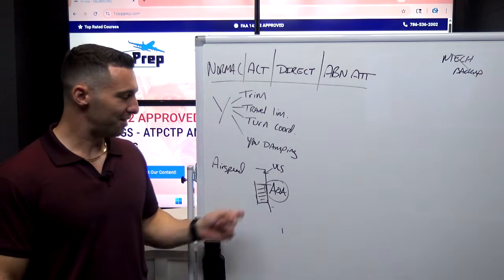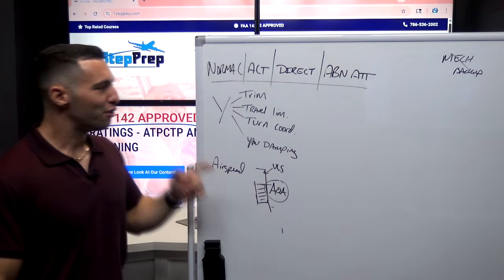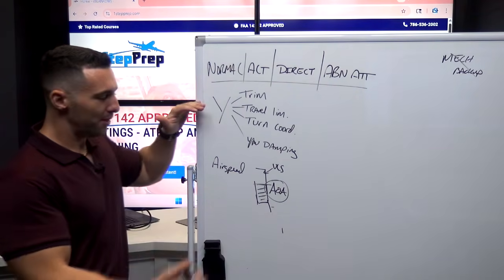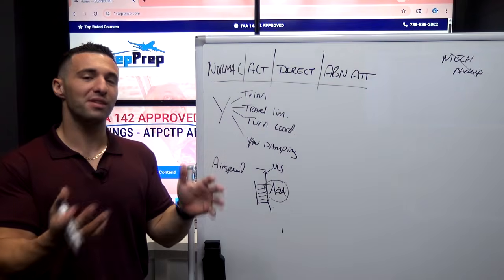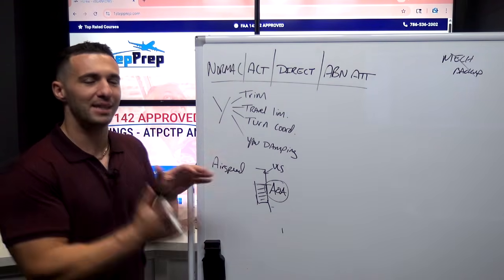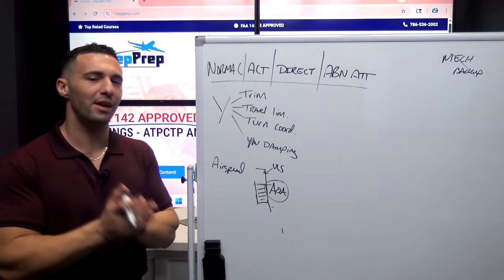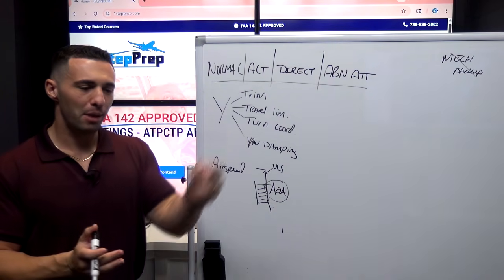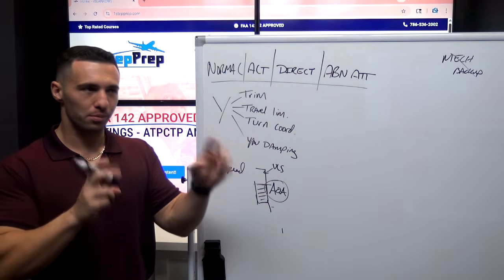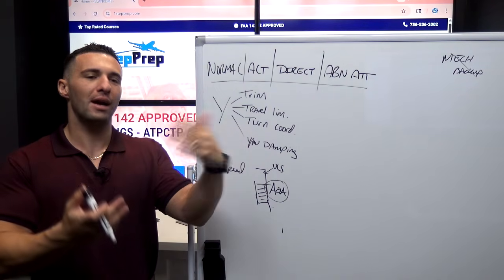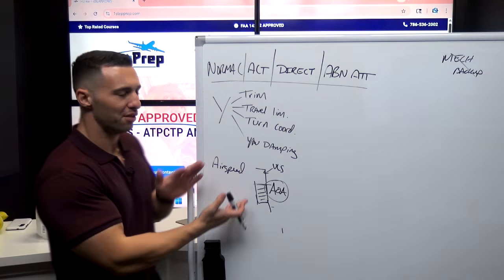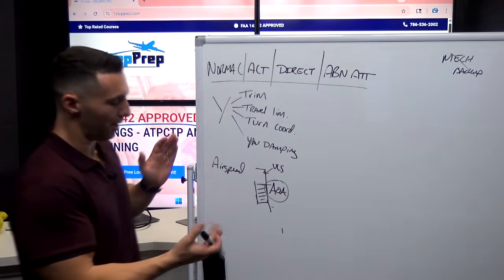Well, because this is an approximation. So the FAC gives me this airspeed envelope presentation with an approximate angle of attack where alpha prot is going to activate, but it's based on an AOA. So you may be sitting in the alpha prot band for a while before it actually hits the angle of attack, even though it appears as though you're buried in it, and you're not quite yet.